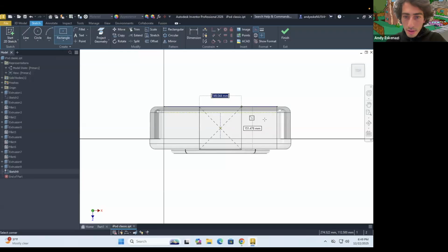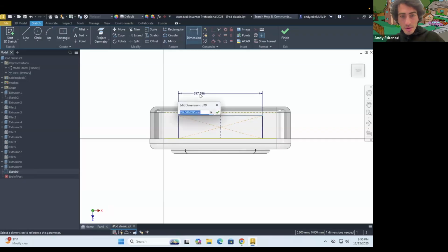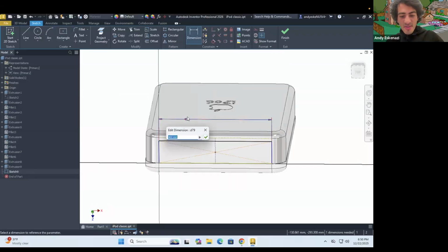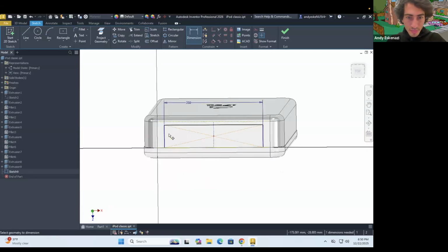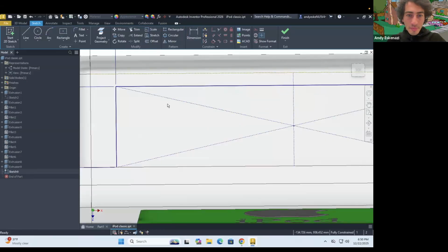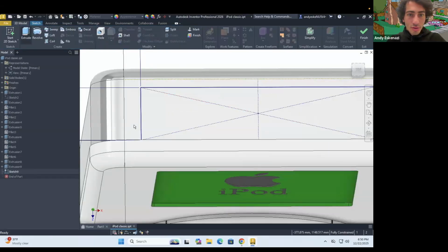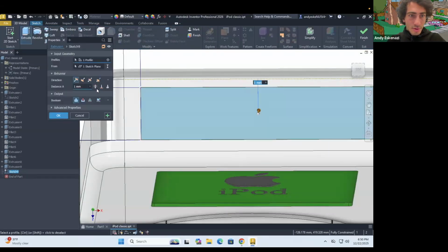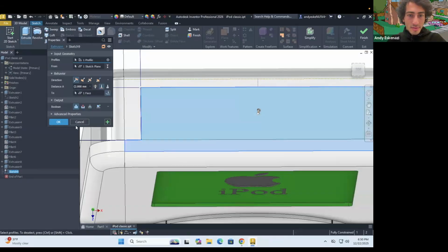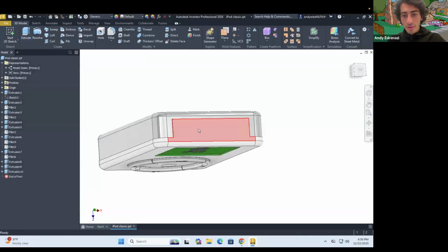We are gonna, oh, well, I actually want to make a full rectangle. It's gonna come like this. We're gonna say, well, that to be 400. Maybe no, maybe 350, like that. Good. 80, that sounds good. Are you fully defined? Yes, it seems like. And we are gonna extrude this upwards, up to that face. So now you see how that's wide too.